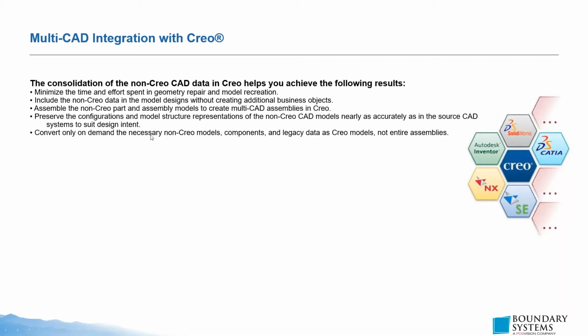You can preserve the configurations and model structure representations of non-Creo CAD models nearly as accurately as the source CAD systems. If your model's clean, it's going to create a model over top of your non-Creo file, and for all intents and purposes, it is extremely accurate. Convert only on demand the necessary non-Creo models, components, and legacy data as Creo models, and you don't have to create the entire assembly.